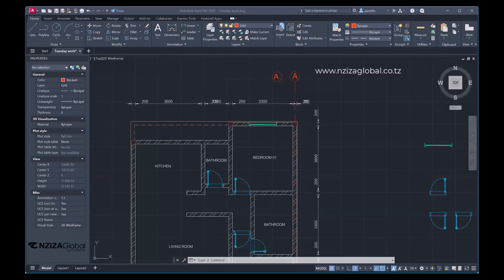This is the only help that can determine the location of those structure elements. If you don't have grids on your drawings, you can't locate your columns and such things. You can't even know how to place your building on a plot. With the help of these grids, you can know where you are going to place your building, where you are going to do the setting out and other things. So that's for civil engineers.